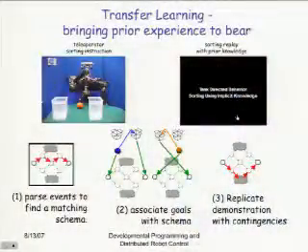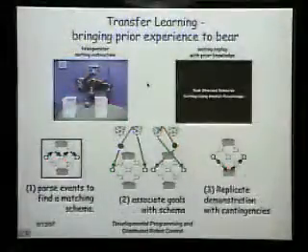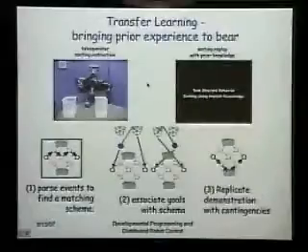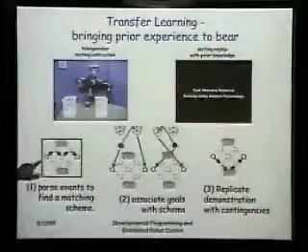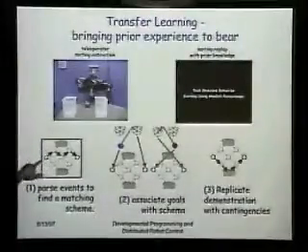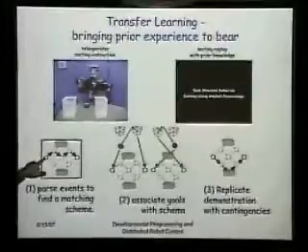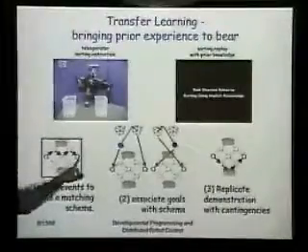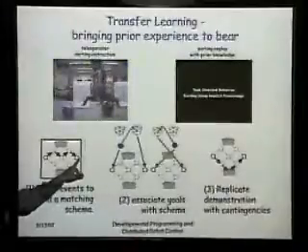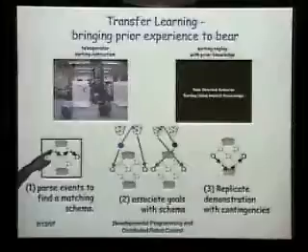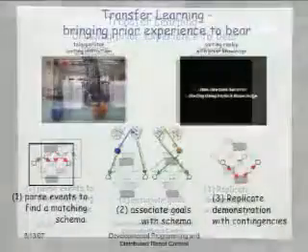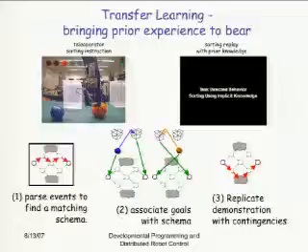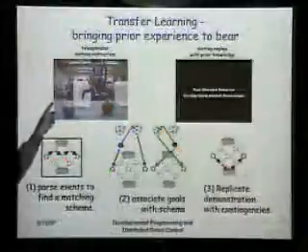So we tried an experiment in which we had a teleoperator, John Sweeney did this work, program the robot. They said, here's a schema for picking and placing. If you look over here, this is a schematic representation of that schema. It has lots of contingencies, lots of transitions, but basically that's prior to the first localize with your eyes, and that's after the last time you touched the object and you left it someplace else on the table or something, right? And there are many paths through here that you could take. You see the teleoperator is not very good at this, but what's up there is a sequential diagram, and basically you're using a hidden Markov model to parse the transitions through that diagram.